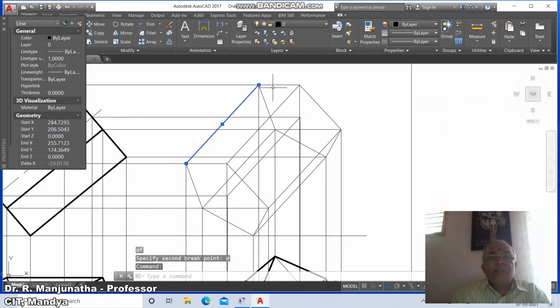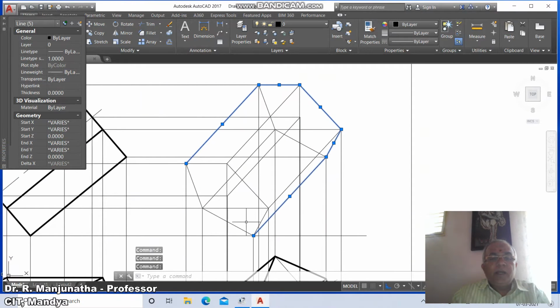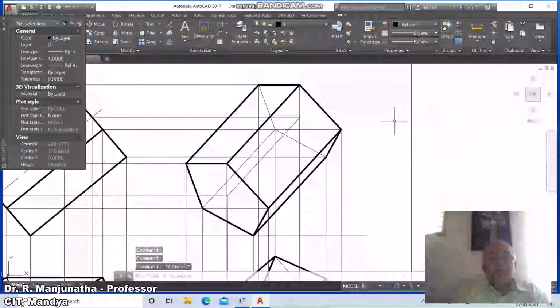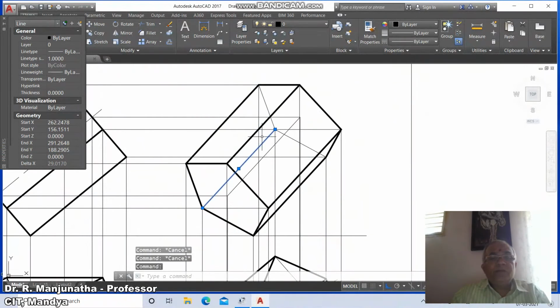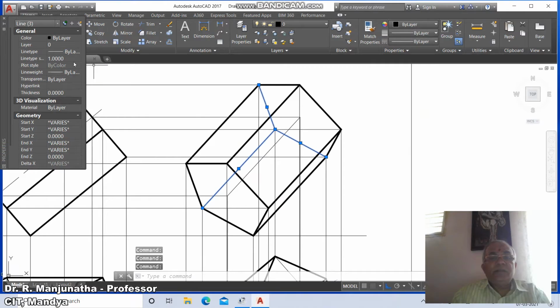Select all the exterior edges of the boundaries of the solids are visible and the surface nearer to the observer is visible. So this line becomes visible, this line and this line will also become visible. So all these lines will become visible. Now the edges which are invisible are this line, because two visible edges can never cross. This is also two invisible edges. So this is also two visible edges can never cross. So obviously it has to become invisible.